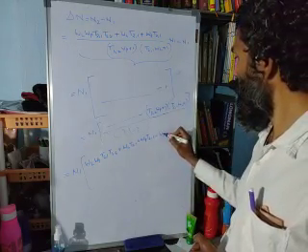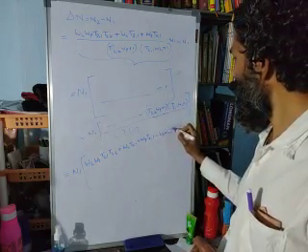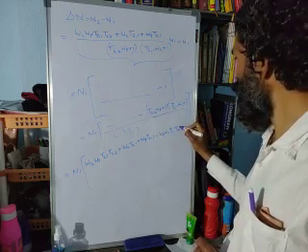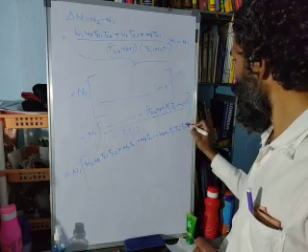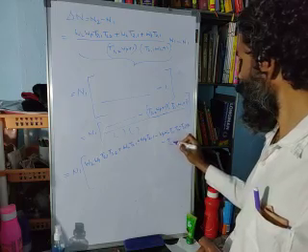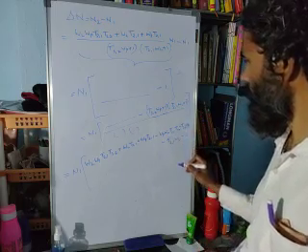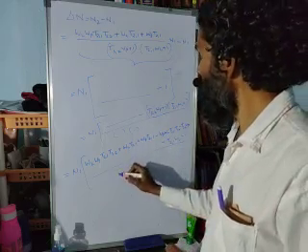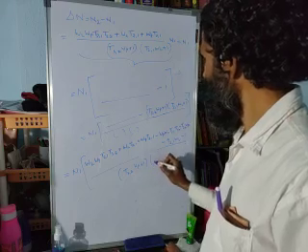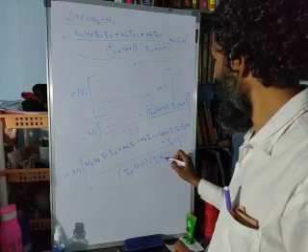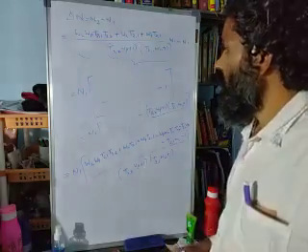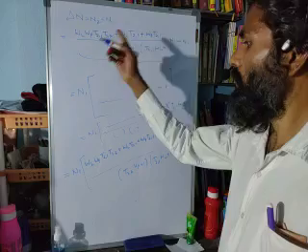And now the product of these two terms. So this is WP WL T21 T32 and minus T32 WP minus T21 WL and minus 1. Entire thing divided by T32 WP plus 1 into T21 WL plus 1, and of course we can close this bracket like this. So this is actually for delta n, which is n2 minus n1.